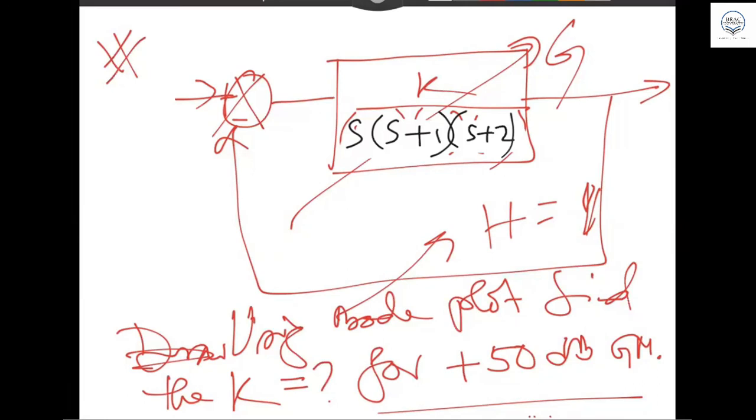If you assume any K value and do your calculation, you see how much you have to shift the curve up or down. Maybe you can assume 2. If you assume 2, then you get 6 dB. So 50 dB means you have to shift it down by another 44 dB. 44 dB down means minus 44, 20 log of K prime, you can find it from there.